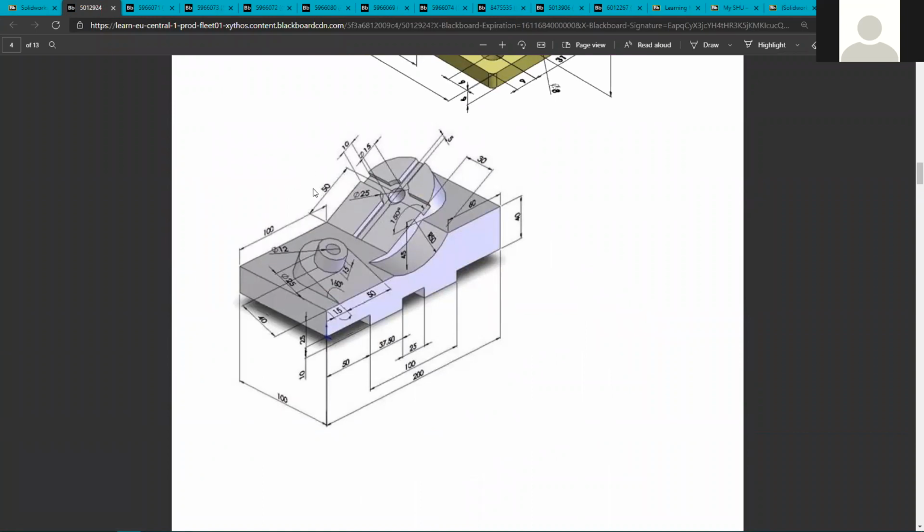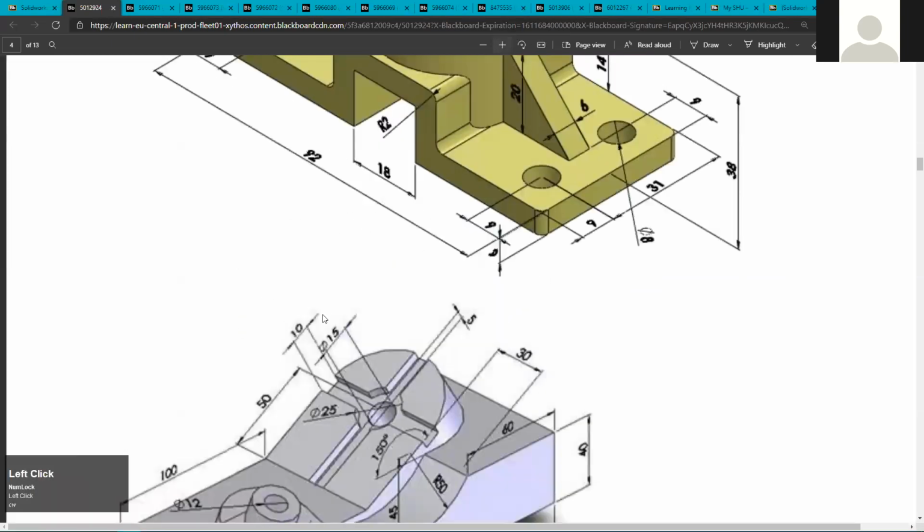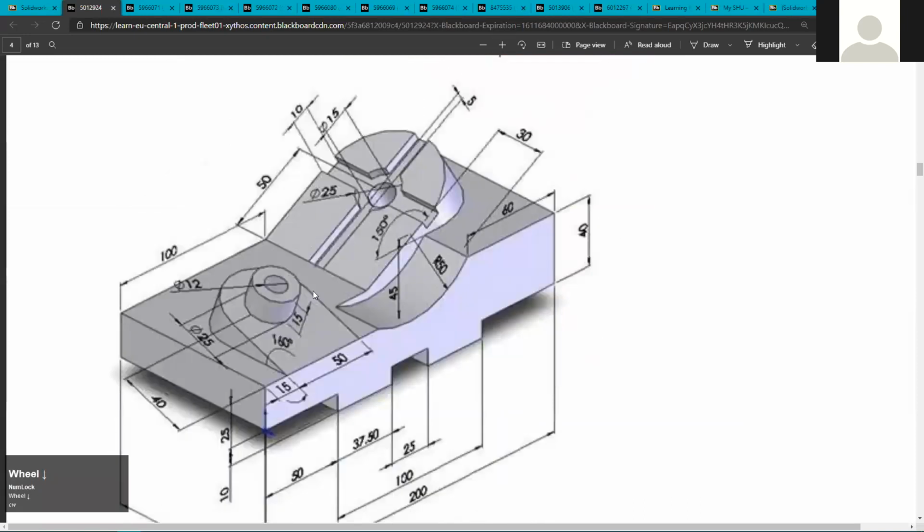There's a few skills related to that one that it may be worth us covering, because certainly these angled faces that you're encountering there kind of require a new skill, which is that you need the ability to put new planes into a part and define where those planes are positioned, and in this case, what angle those planes have relative to the base planes.